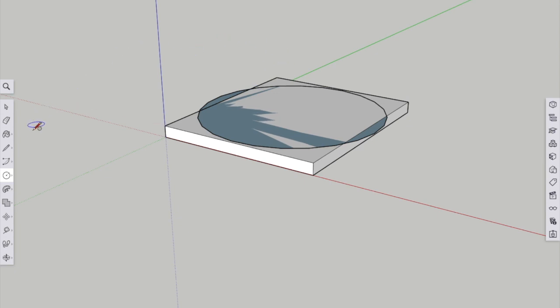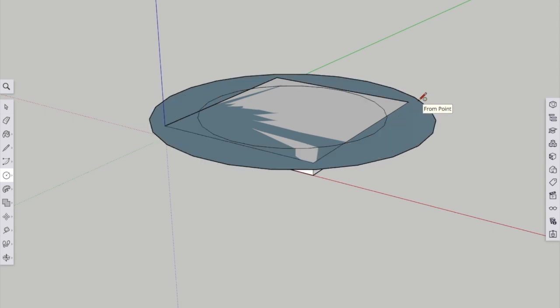The next step, I'm going to draw another circle, and this circle I want concentric. You'll notice that there's no point, so I'm going to have to hover over the other radius, and then draw my circle. This one is a 12-foot diameter circle. This 12-foot diameter circle is going to become the belly, or kind of a midpoint of this treehouse.